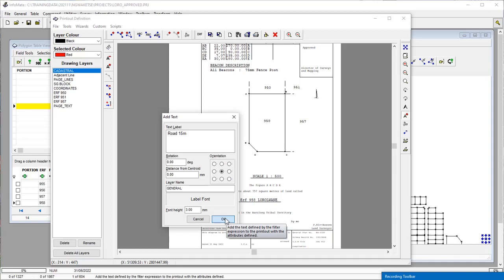With that, we are then able to directly print this diagram. It's probably not finalized, but there's not much to do here. But when it's finalized, you can set up your printer and then just print it. Or alternatively, if it's a complicated one, you can use this option here to export it to DXF and do the final touch-ups in DXF in MicroStation or AutoCAD.